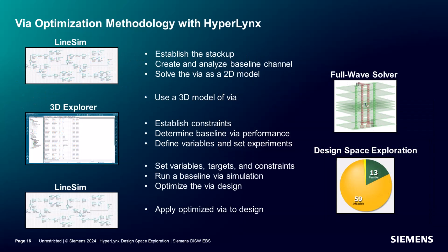A few tools would be used in this process, starting with LineSim, the schematic tool, to establish a baseline and verify the channel margins. 2D modeling in LineSim is quick and easy, and it's calculated through the VIA visualizer. However, these are just rough electrical estimates. If we want something more accurate to view the performance of this VIA in the real world, we'll want to simulate with a 3D model.